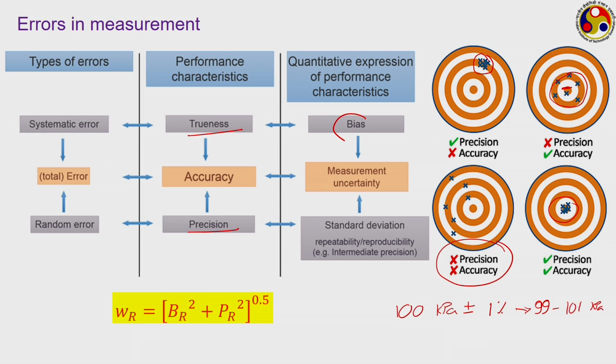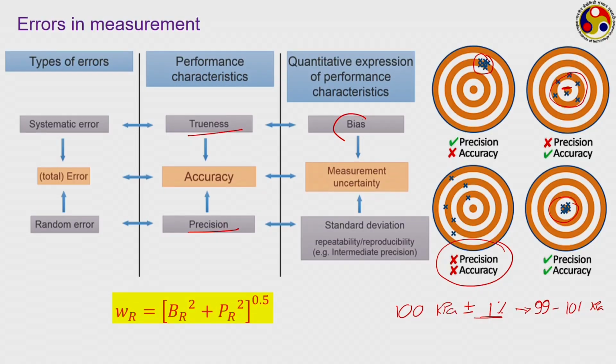Actually, whenever we are getting such plus minus some percentage or some fraction, be careful about the details. More often than not, this refers to plus minus 1% of the value, but there may be several situations where actually it is given as plus minus 1% of the full scale of your instrument. That means, suppose the same pressure gauge can give you a reading up to 400 kilopascal.